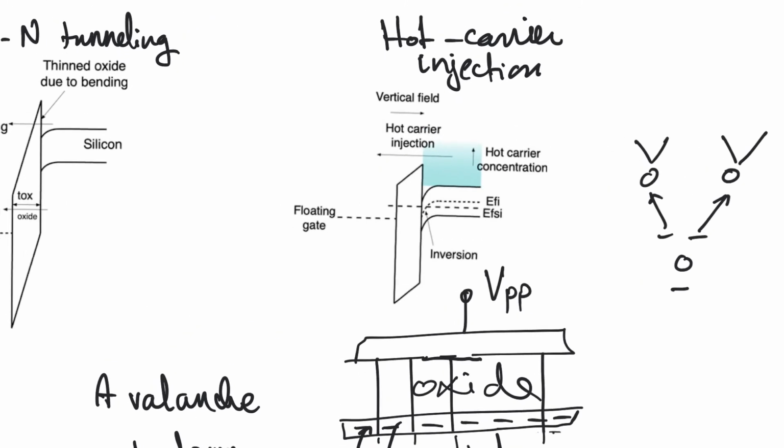Something that is a little bit more gentle is the hot carrier effect. And we discussed the hot carrier effect in detail in a video in Module 10. But the hot carrier effect is basically a classical effect. It can be understood fully using the band model. There's no quantum effect happening here. Some electrons are going to be very energetic in the conduction band of the substrate.